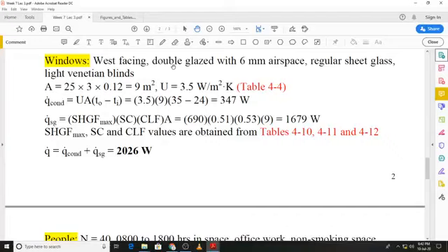We are also given the roof type, roof number 4, which has been marked out. Now you have the time, and we need to find the cooling load at 1400 hours. This is the column that you will read the value from, and once we have the right roof type and the time, we can find the CLTD value.